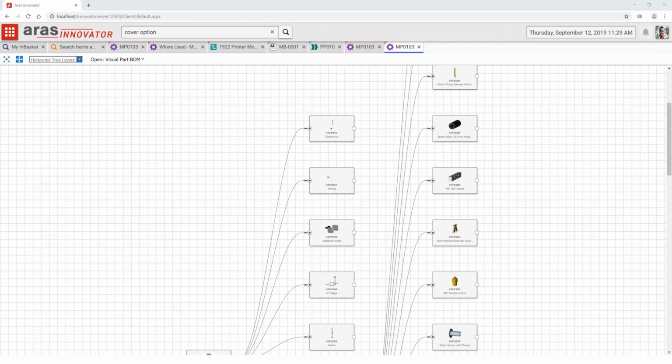So the viewing of the CAD models from various native formats is attainable by using a component called a conversion server that we supply. If you're a subscriber, that is something that's supplied. That does require a separate, one-time installation for the conversion server, configured to match the type of CAD systems and graphics you're using, and from then on it's automatic.